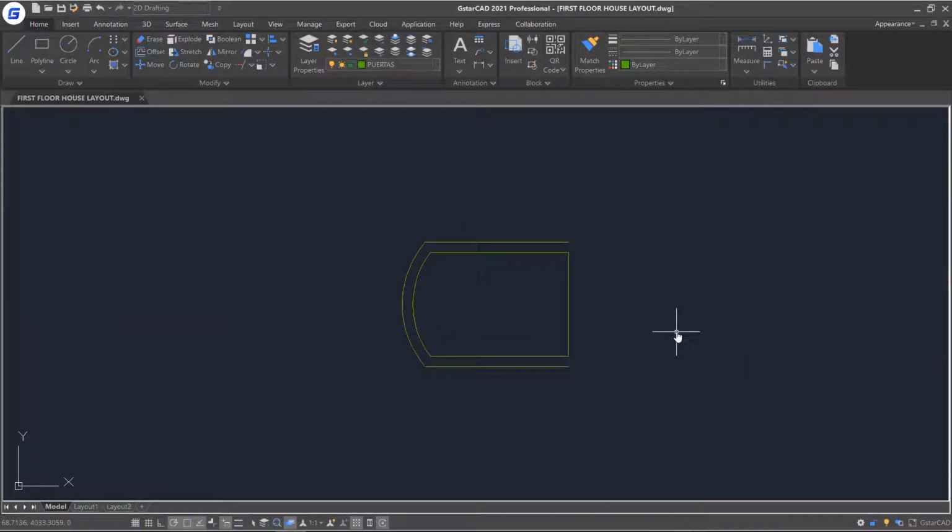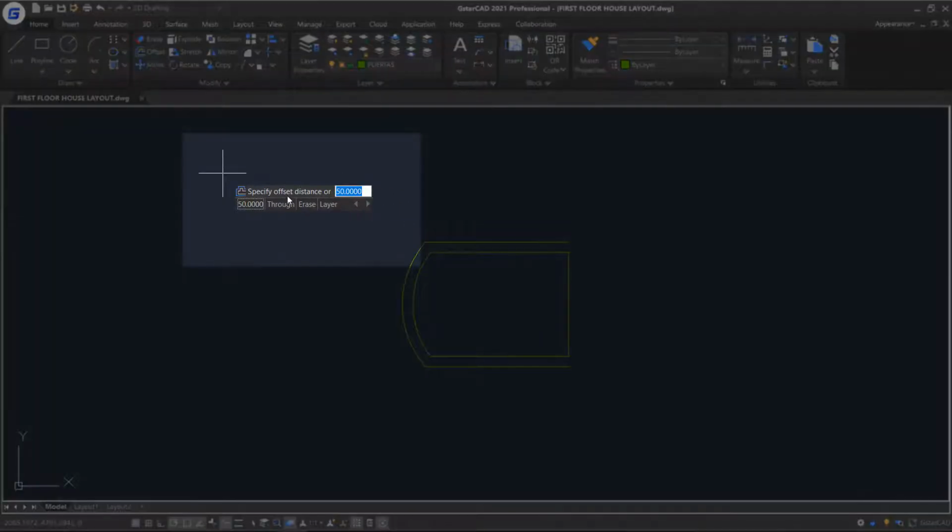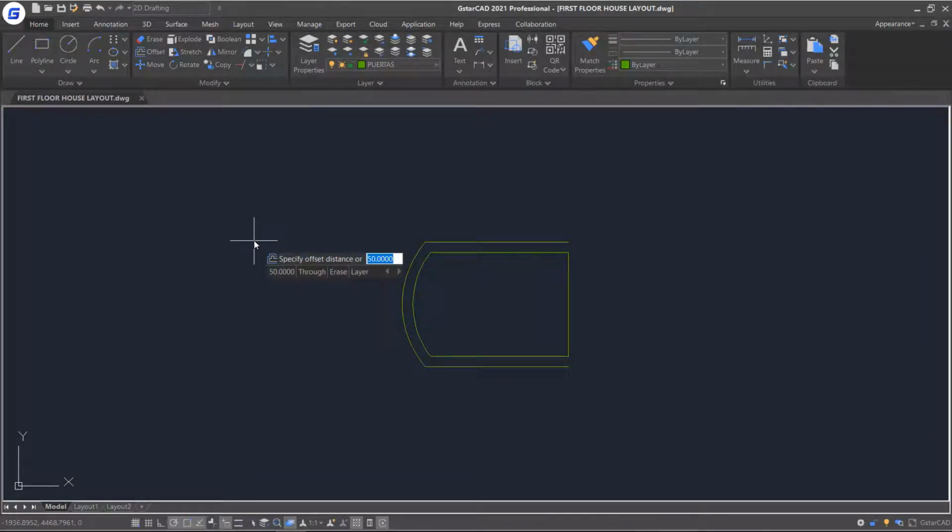In this part, we will introduce the offset command for offsetting geometry in the drawing. Click the offset command, select the erase option and set to no. Select the layer option and set to source to apply the source layer on the selected object for offsetting. Then enter distance or select a through point. I will use distance first. Enter the distance value directly in the dynamic input box. Press enter, select the object, and click on one side to offset. After offsetting, you can continue to offset objects, or you can select the exit option to end the command.